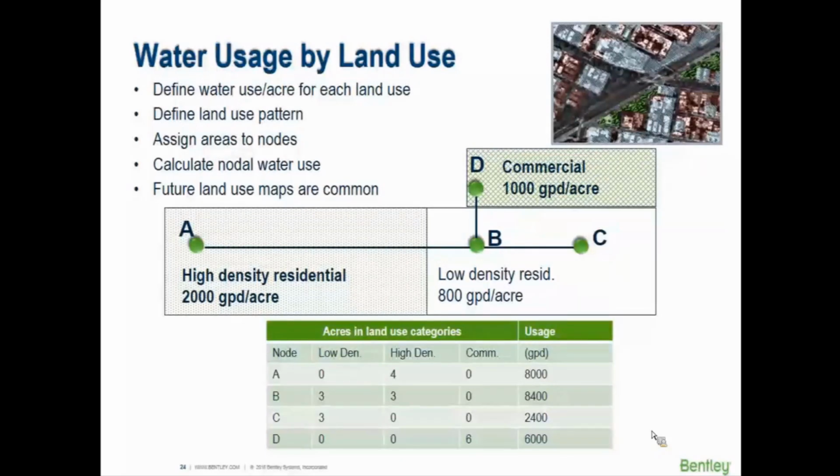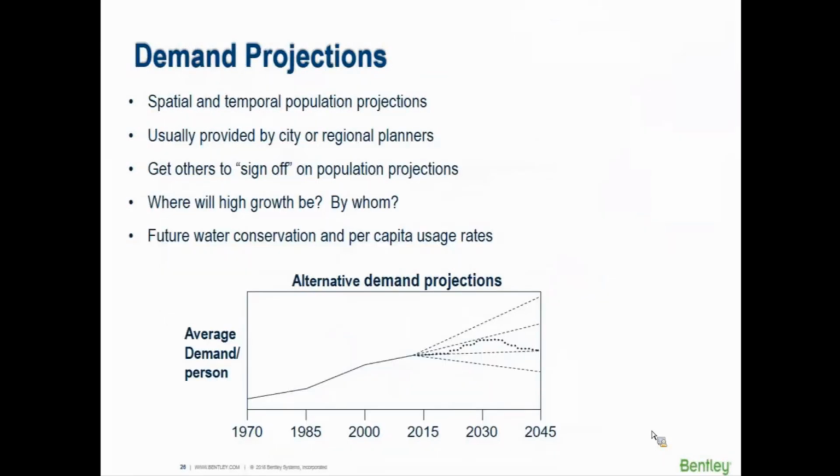When you would use a method like this to load a model, that would be planning or some future kind of model, and you're not quite sure what's going to go there. So probably not a very common one if you actually have flow meters in the area. Peaking factors and figuring out what demands are going to be in the future. What's it going to be like in 2030? Where your demand's going to be, average per person.